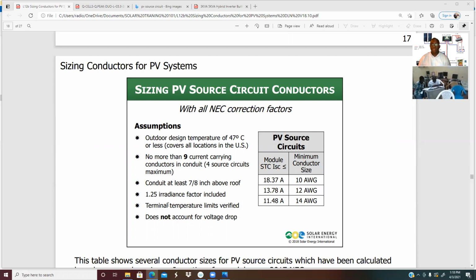So they made it very explicit here that your conductor should not be on the roof. It should be lifted up from the roof. There should be a space between your conductor and the roof. Don't lay the conductor on the zinc. We have to elevate it off the roof, because if you lay it on the roof, that's a bad job. Your conductor or your conduit, whatever it is, should be off the roof.